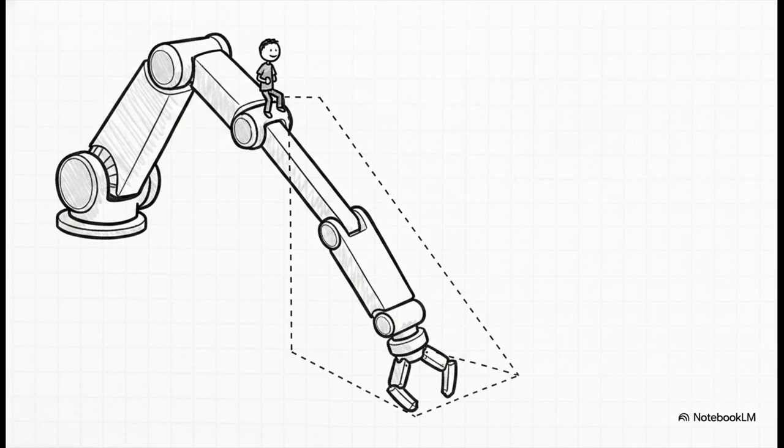So imagine standing on joint B looking up at grip A. What do we see? Well, the arm is 1.6 meters long, angling down at 45 degrees. Just like we did for the base, we use trig to map this position. This is RA/B, the position of A relative to B. The calculation gives us roughly 1.1314 J and a negative 1.1314 K, since it's pointing downward relative to that joint.